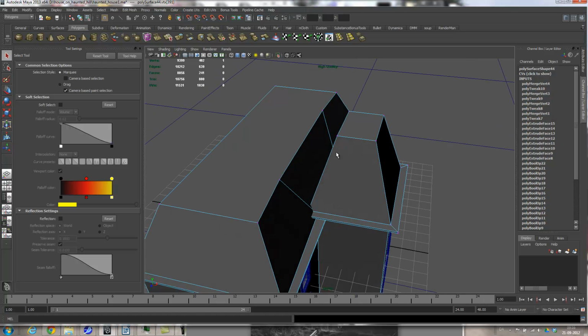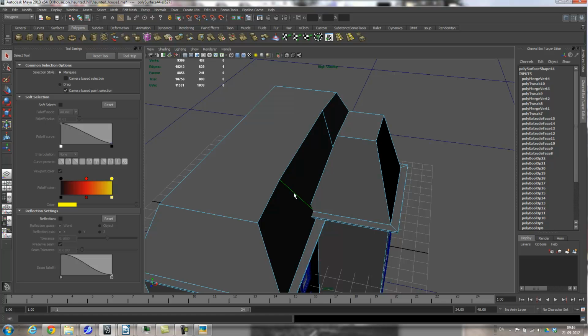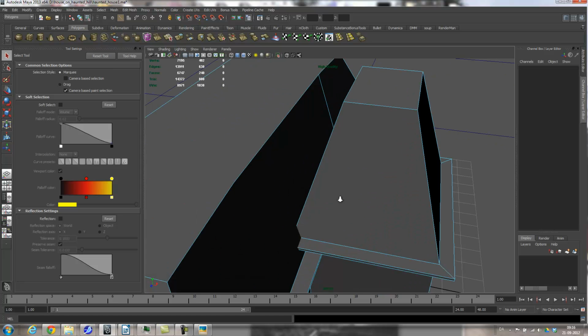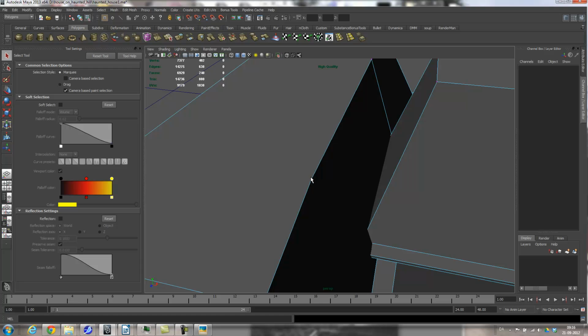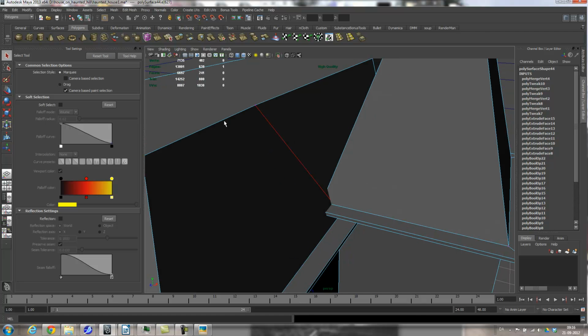And actually I can just get rid of these lines here altogether if I like, and grab these, and then I go edit mesh, and instead of just clicking delete, if I just delete this, press delete, you'll see that it'll keep its shape and it will actually have a dead vertex in there. So to not do that, I'll just select it, and I just make sure I have it selected.